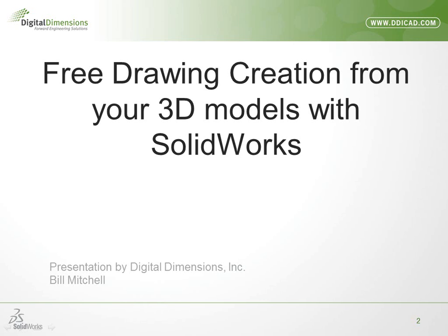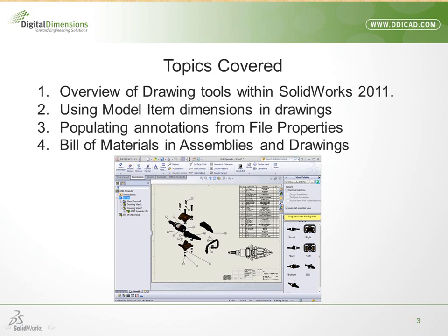Some of the stuff that we're going to cover in this webcast is an overview of the drawing tools within SOLIDWORKS 2011. Some of that's going to include using model item dimensions in drawings. Model items are basically the dimensions that you assign features inside of a 3D model. You can leverage that information inside of your drawing files to minimize the amount of work, and you can also edit those directly. So I'll show you how to use those features.